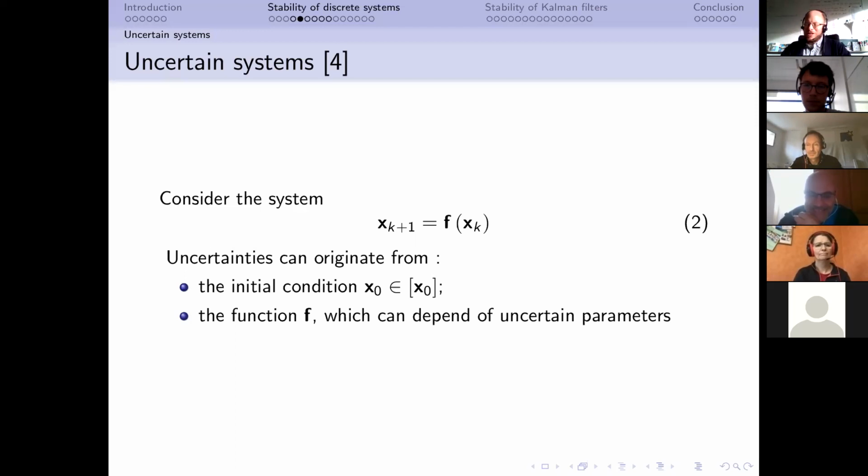I think you could say at that point it's something like you have some dynamic observer model using some gain adaptation scheme, and the gain adaptation scheme just is motivated by the structure of an extended Kalman filter. And in such a way, if you formulate it like this, you get away of the Gaussian interpretation of noise or estimation covariances, for example.